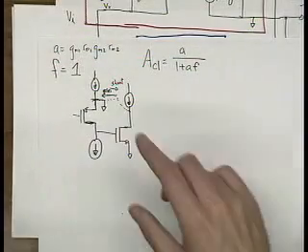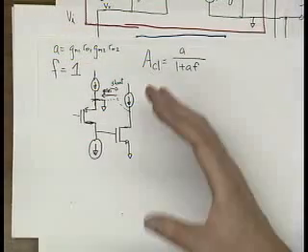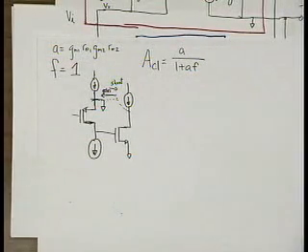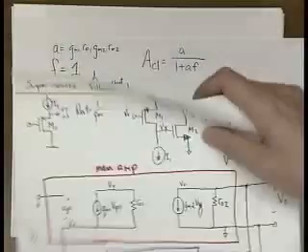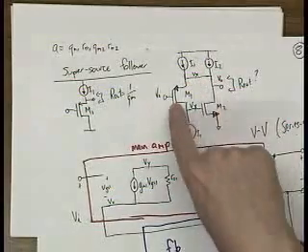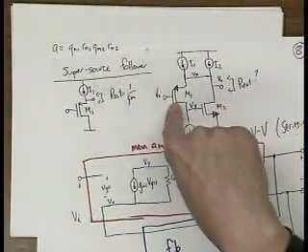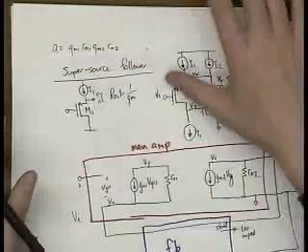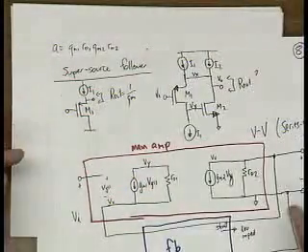And that step that you do, I think is the hardest part of feedback. When you break the loop and figure out the resultant circuit, it is a little different from what you had here. Because here you've got infinite source degeneration on this guy, so you'd think it's got no gain. But in reality, when you break the loop, you ignore that portion of it in this case.